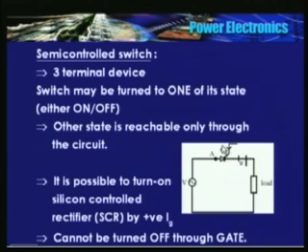Having turned on the device, you cannot turn it off using the gate. I will repeat: when the device is forward biased, by supplying a positive gate current, the thyristor or SCR can be turned on. But having turned on the device, you cannot turn it off using the gate. Hence the name semi-controlled switch.